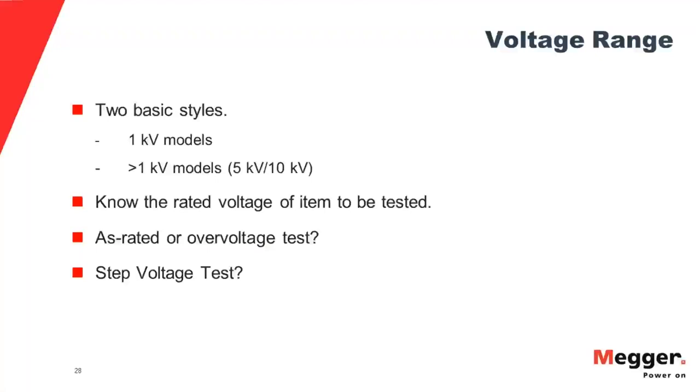For many years, the medium voltage testers jumped to 5 kV. And then in more recent years, higher voltage tests are becoming more and more significant for standards conformances, and also because the insulating materials coming on the market are becoming more and more developed, and higher voltage testing, 10 kV, 15 kV, and so forth, is becoming more prominent. So for many years, if you didn't buy a 1 kV tester, you bought a 5 kV, but now you have more options to go up to higher voltages.